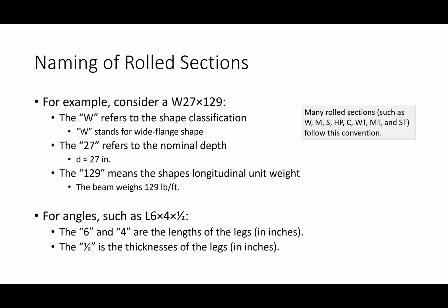You always put the biggest number first. You don't do an L4 by 6. It's always L6 by 4 or L6 by 6 or L8 by 6 or what have you. It's always the biggest number first. Okay, so this is how these sections are named in the manual.